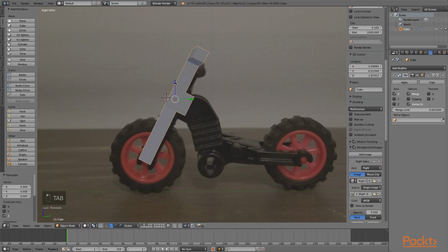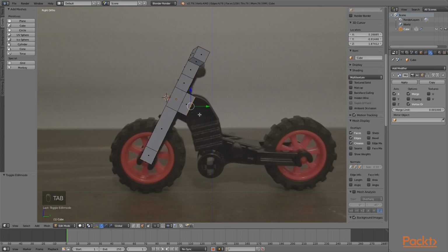circular type curve. So what we can do is be in edit mode, make sure this face is selected. Go back to our side view, numpad 3. Press E for extrude. Kind of bring it down. We can also hit R for rotate and do it on the x-axis and kind of give it a nice curve right there. Which I'm going to do Command Z and kind of go back. Let's rotate this just a little bit. And this is where creating an object is all how close you want to make it to the real thing. I'm trying to follow this exactly how it wants to be.